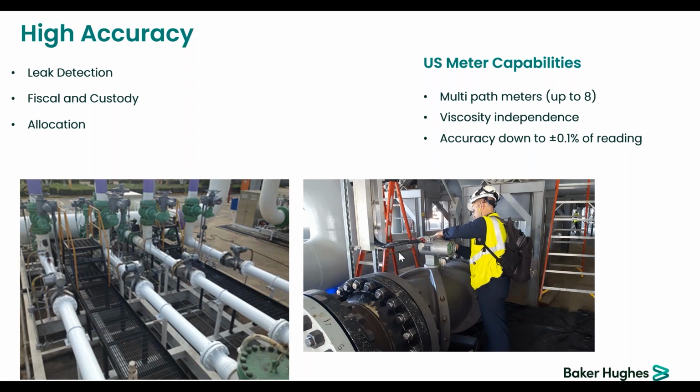And the photo on the left is a metering station for oil, and we replaced turbine meters there, not because they were not accurate. It's simply because they were having a lot of operational expenditure costs because of the drift over time, because of the, let's say, lifetime of the bearings, the blades, etc.